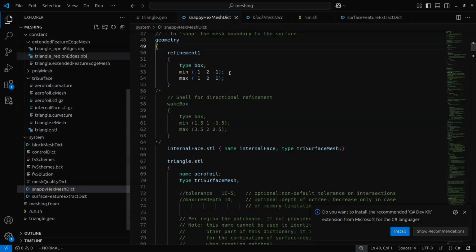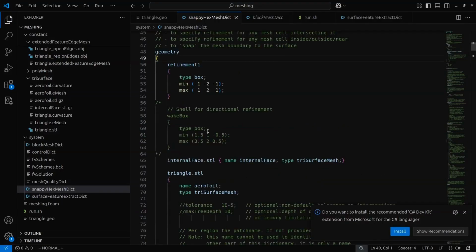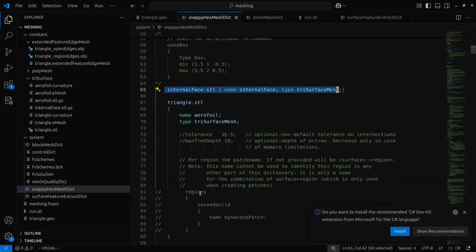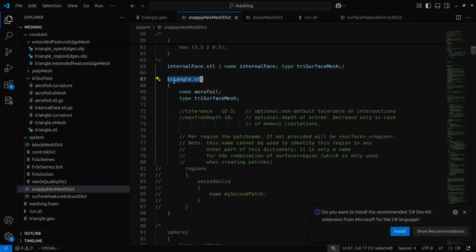Now let's go to SnappyHexMesh. In SnappyHexMesh, you can define geometry here, whatever geometries are going to intersect, or some additional faces that are not the geometry feature but help to create better meshes, which we'll see later in this lecture. This is how you define a geometry. You can type the file name here, the actual name, and then put a label to this. And you can do it the other way around as well. You can put the label here and write the file as the file name here.